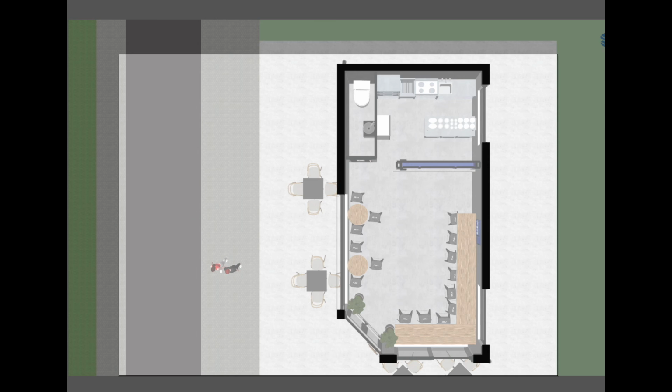Skills Task 2 will help me in developing my major product, as I chose to do a full drawing set consisting of floor plans, elevations and vector drawings. And having done a floor plan for the cafe, I now feel more confident in doing so for my major product, as I have discovered many new skills which will aid in constructing my drawing set for my major product. An example of this is now being able to export a parallel projection top view using the section plane from SketchUp and then creating a precise 2D graphic displaying the layout of the cafe.